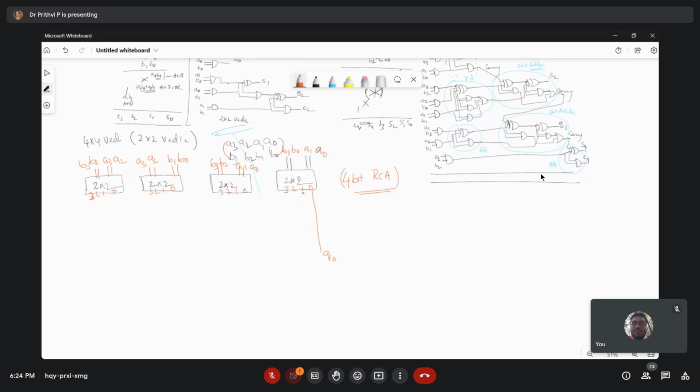No, ma'am, listening. Yeah, this is Q0 and this is Q1. That means I'm taking the quotient sort of thing. Or, if there is a confusion, let us take this as S0 and this will be the final S1. S0, S1 will be directly coming at the first stage of 2-bit Vedic multiplication. And the next set of these two, the 4 outputs we are getting here, will be taken as the inputs for one 4-bit ripple carry adder.